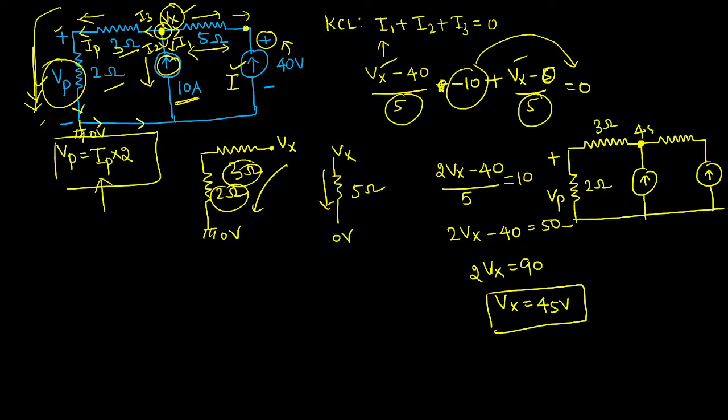So here I found 45 volts. Now see, the first conclusion is 45 volts. Here we have 0 voltage at this node. Current will flow from higher potential point to lower potential. This is the direction. In this entire branch, the total resistance is 3 plus 2, 5 ohm. Then what is the total current?